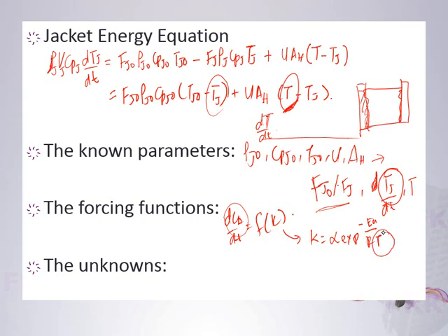You will actually run this within a range. So you have to solve for your CA. So you have to solve for your T. It ties. So once you solve for volume from your TCE, you can solve your CA. Then you can solve for your T, temperature of the reactor. Then after that, you can actually manipulate your TJ. So this is a complicated equation. Use your Excel. Use your iteration method.